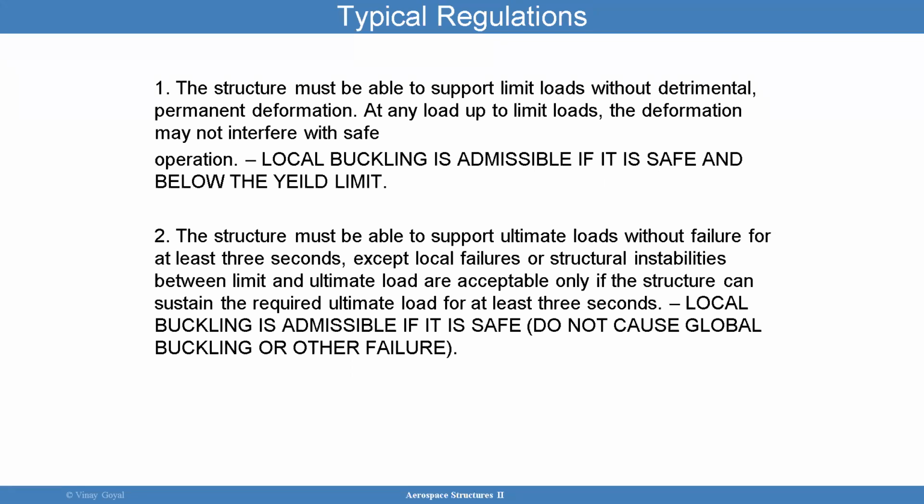If you have a Minute Maid can, like I showed, and that can was pressurized, when I compress it, I expect that to take a higher buckling load than if it had no liquid inside. So as a consequence, if I have a factor of safety that needs to be applied, I will apply it to those loads that cause buckling to occur, that cause the instability.